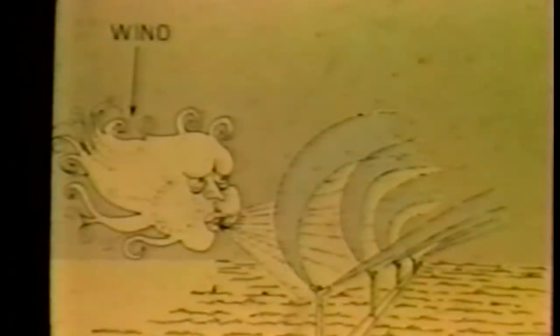Wind action also affects the water application method by distorting the water distribution pattern. Strong wind action may distort the water distribution pattern of the sprinkler method to the extent that you get little water on the windward side of the sprinkler and too much water on the other side. Often, high winds may affect the application efficiency of surface irrigation. This is particularly true on large, unplanted level areas.